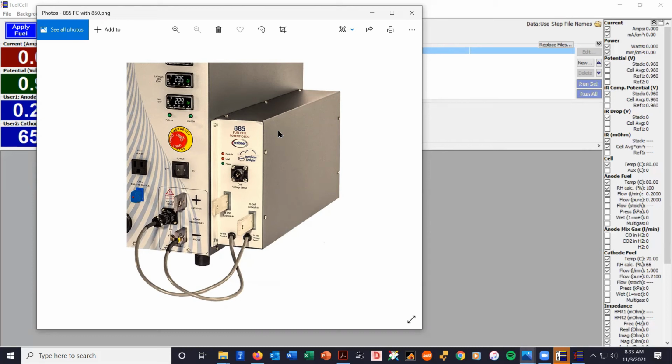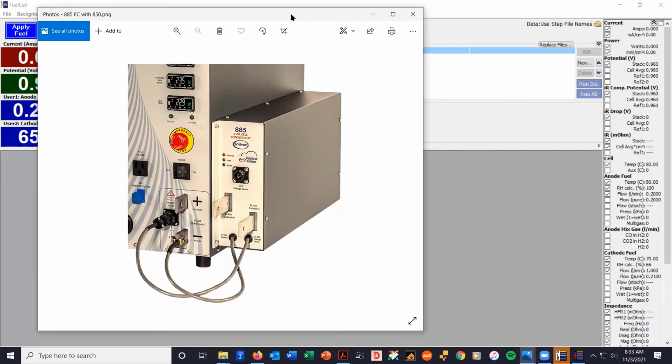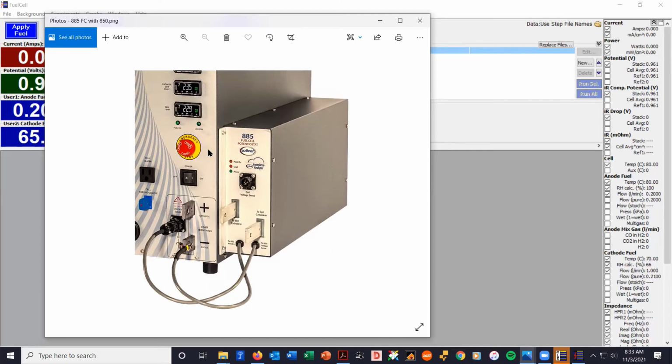It's an option, just like in the 850. It's an option whether or not the equipment has the impedance analyzer installed in it, because you're not using the impedance analyzer in the load in conjunction with the 885. They're completely separate instruments. If you want to do impedance using both instruments, you have to have the impedance analyzer in each instrument separately. So it's an option in each.